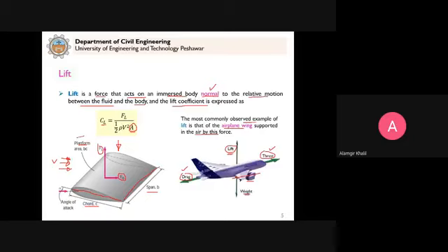So that's why this is the planform area, and it is given simply by b into c. Okay? So normally, remember, for this area, even in the case of drag forces, we just consider the projected area on a plane that is perpendicular to the force vector, either the drag force or the lift force. So this is important, the characteristic area.